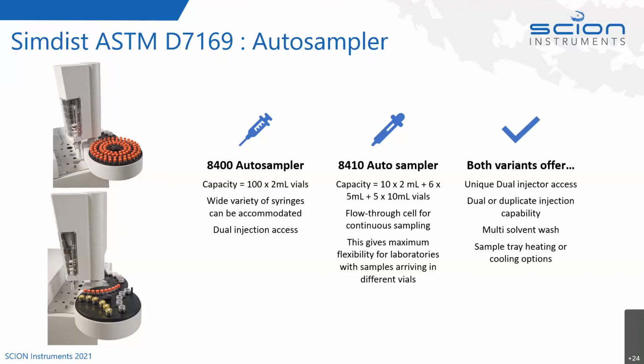What I would say is the tower moves, and the tower moves in an arc, so it can cover 2 injection ports. But by moving in an arc, the injector, the syringe is not held above the injection port. And this is important because we're going to inject carbon disulfide, which is very volatile. So this means that the tower will move away from the hot injection port after each injection,